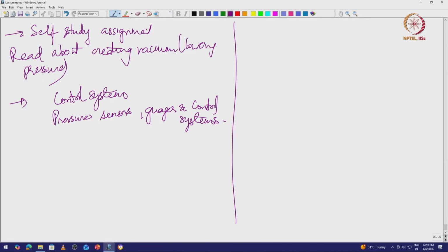The sensor reads the pressure, and then a PID control exists there. Using PID control, you can set a point at which the pressure should be. Once the pressure increases beyond that, the controller gives feedback so that it decreases; if it decreases below, it gives feedback so that it increases, so that it stabilizes at the set point. PID is proportional, integration and differentiation. It uses all these processes to stabilize your pressure to a set point. That is again the theory of control systems.